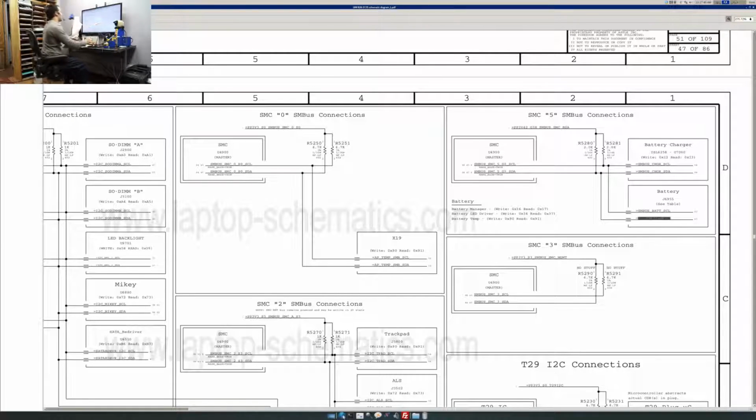So you have PP3V42_G3H. If you've seen my other videos, you understand that these are just basic voltage rails. Don't be scared by all that. PP3V42 just means that that's where 3.42 volts is. That is a power line on the system. The system has a 12-volt power line called PPBUS_G3H. It has a 5-volt power line called PP5V_S5. You have PP3V42, which is a 3.42 volt power line. So that's the 3.42 volt power line of the system.